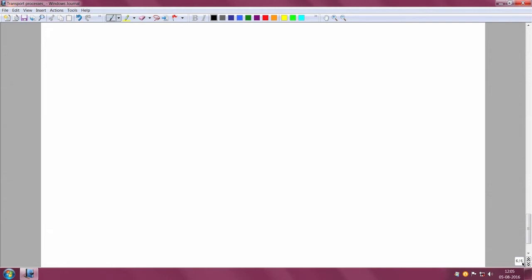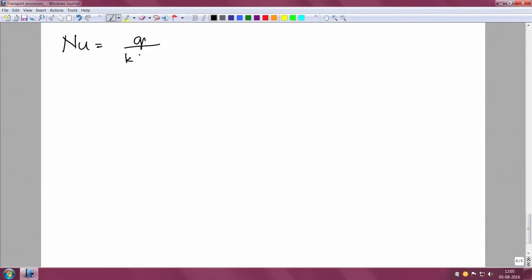We know, of course, that the fluxes change when you impose a higher velocity of fluid. For example, if the flow around a particle is faster, the fluxes change. However, that is what is taken into account by the correlations. So, for example, the Nusselt number can be written for the heat flux as the heat flux divided by kΔT/D, where k is the thermal conductivity, T is the temperature, and D is, let us say, the diameter of the pipe in the case of the shell and tube heat exchanger.